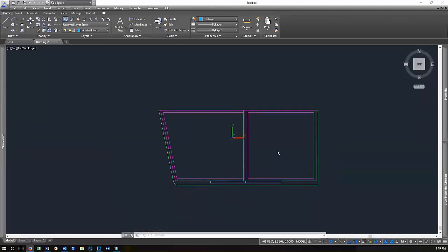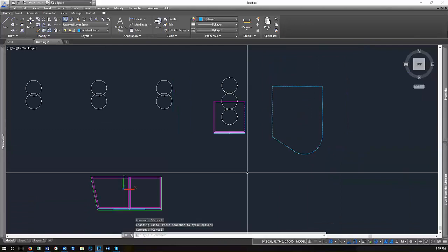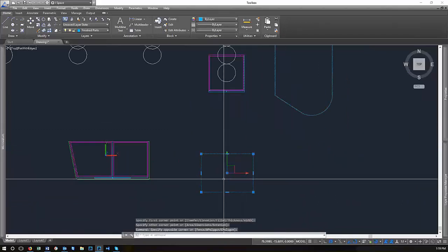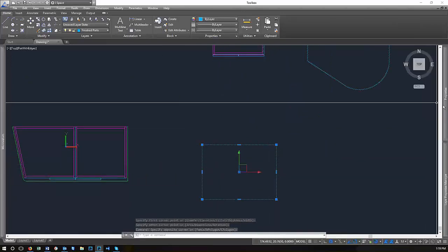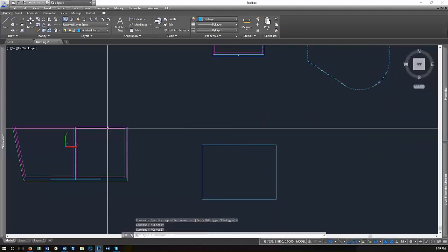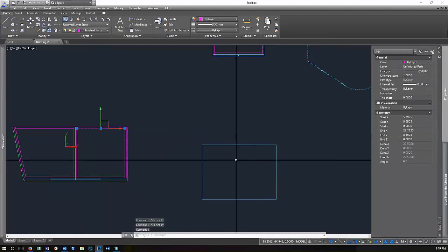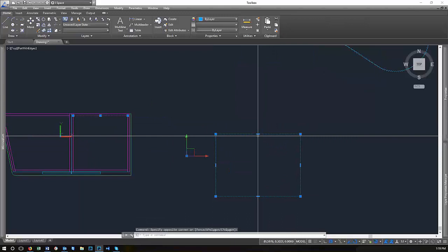Okay, another useful command. What we did here was called a polyline. Anytime you start with a rectangle command and lines are grouped together like this, it's technically a polyline object. You can see here it's a polyline, whereas the regular lines that are not grouped together are just called lines. Polylines are especially helpful in some cases because they stay together.